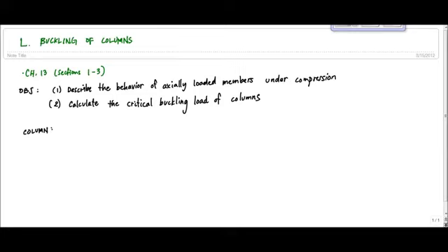So a column is defined by, when I look on the inside, I have axial compression. Doesn't matter if it's a member of a truss. It doesn't matter if it's vertical, horizontal, or sideways. Essentially, all my other internal loads are zero, except for my axial force that is in compression.